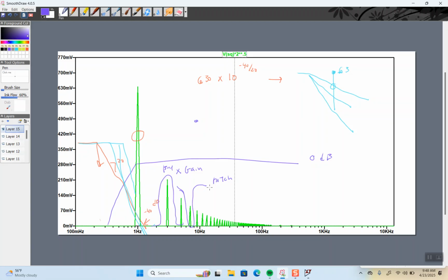And with the pulse width modulated DAC, it's a square wave that comes out of a microcontroller with one pin. So this is a digital signal, but how long it stays on is actually like an analog signal. Is it on all the time? 50%, 25%? That's changing in time. That's where the information is, but it only takes one pin, right?